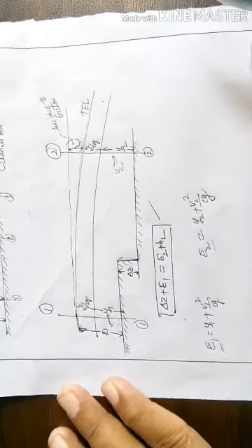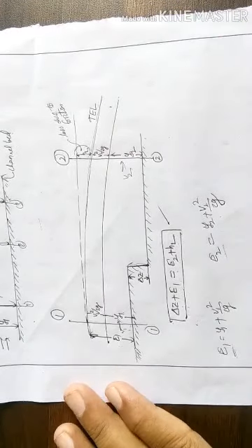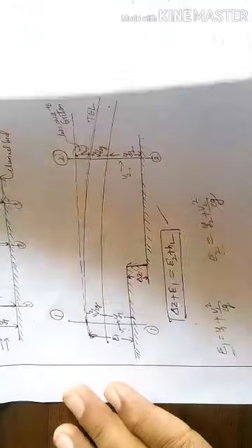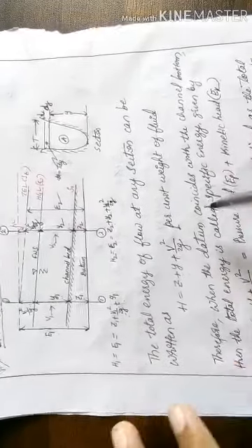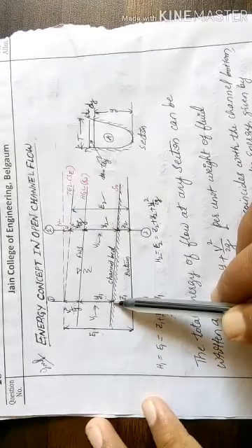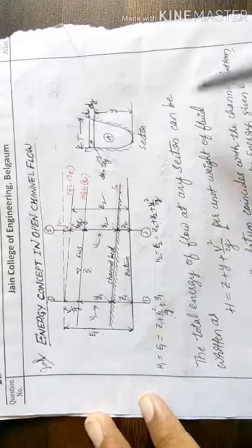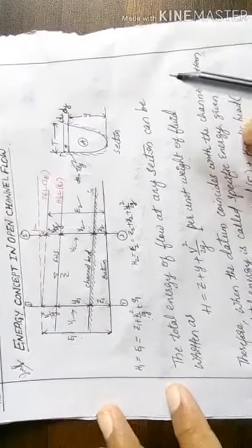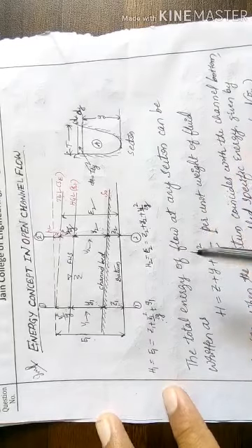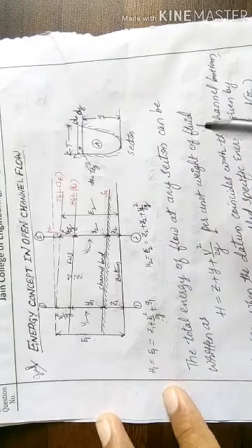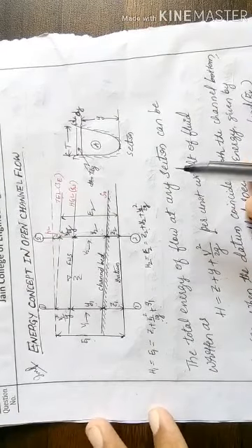This is the concept of energy even in a hump and a drop. So again, just remember what the specific energy is. The specific energy is nothing but the total energy, but it is measured with respect to the channel bottom. So this is a very important concept in channel flow. In the next lectures I'll be drawing the specific energy curve, how it can be drawn, and from that curve we can understand various things that we'll discuss in the next class.